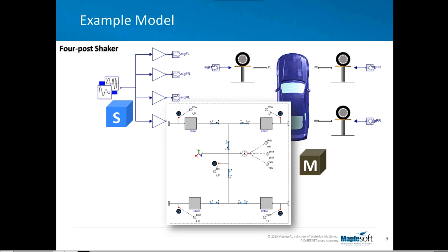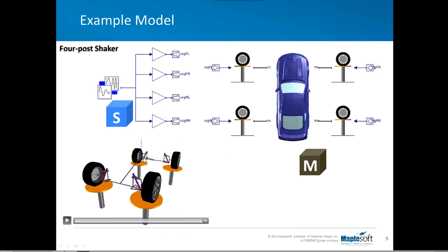So if we look at the vehicle body in the middle here, this is how the subsystem looks. You can identify the rigid bodies which incorporate the mass and inertia tensor for the main chassis, and also representing the unsprung mass that will move up and down with the posts. And there's a sensor for plotting the measured roll, pitch, yaw angles for the main chassis, and a visualization component to basically visualize how the vehicle orients in space. And if you look closely, you can see that the visualization is in the middle here as I rerun the animation.